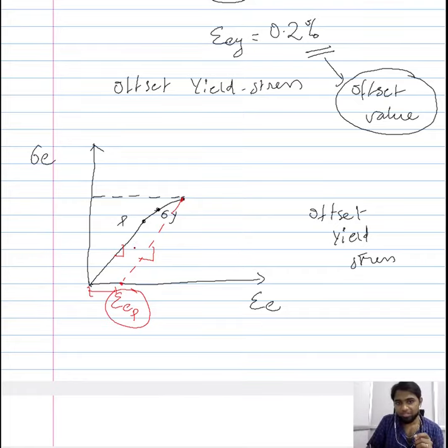If we refer to the slope here as E, then the line that you plot in order to calculate the plastic deformation exhibited by the material at this point should also have slope E. When you draw a line from that point with slope E, parallel to the elastic or linear relation, you would end up with a definite plastic strain, and that plastic strain is what is present in the material. Even without unloading it, you would be able to calculate that amount of plastic deformation.